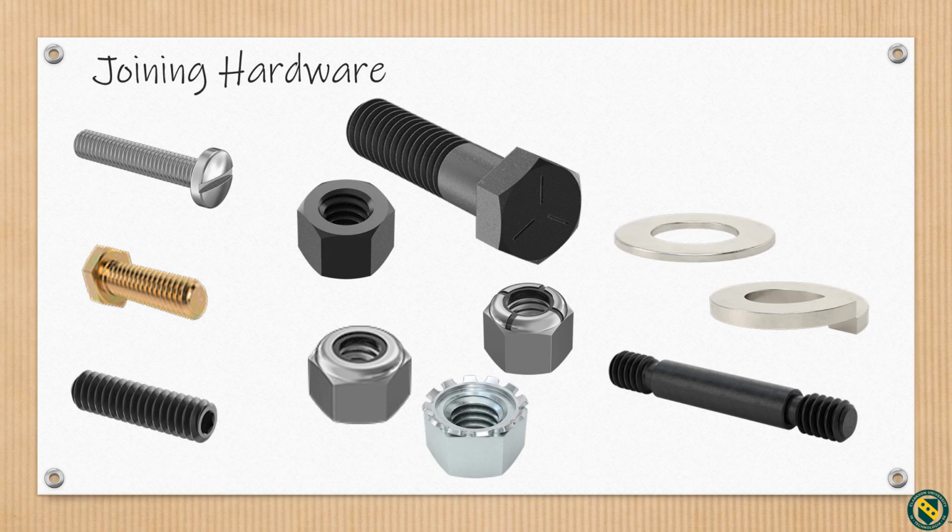A washer is a part having a centrally located hole. The washer performs various functions when assembled between bearing surfaces of a fastener and the part being attached. A washer face has a circular boss under the head of the fastener, providing a bearing surface. A split washer helps prevent loosening from small vibrations.